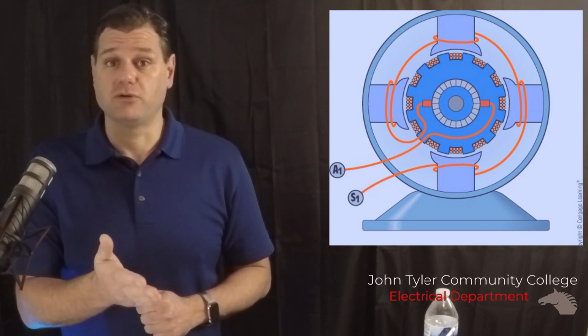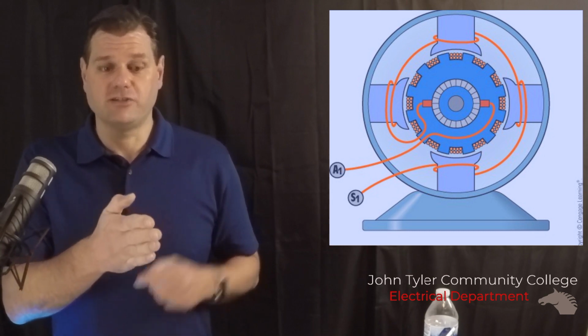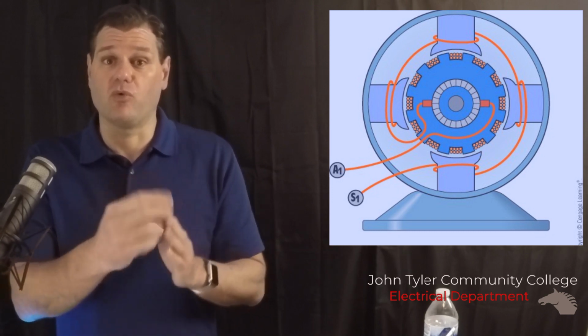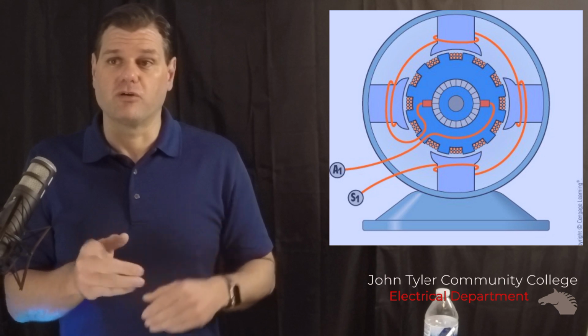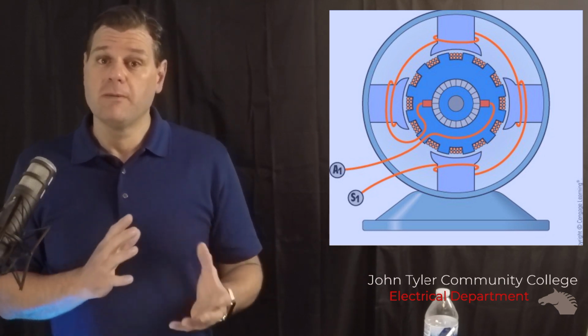We don't see A2 in this drawing because they've connected them in the drawing, but you'll typically see A2. A2 will be connected to S2 and be under a wire nut together. They're just put under one solid wire, so you see it come right off the brush, and it leaves and goes right to the pole piece.